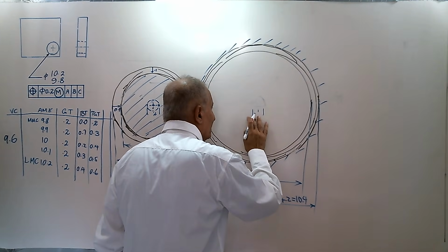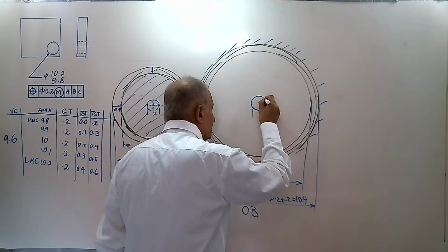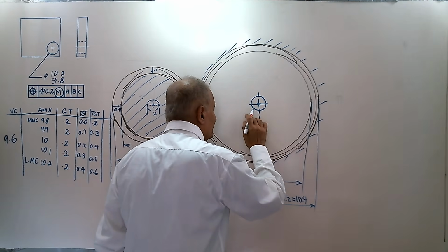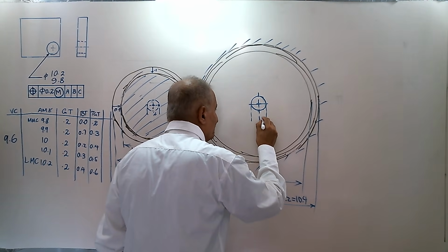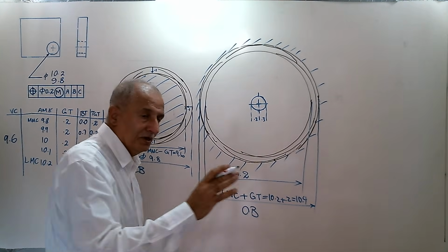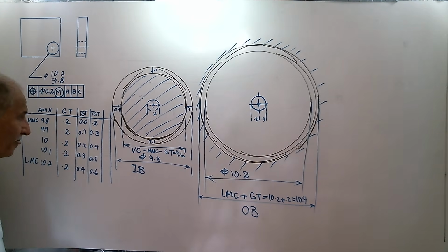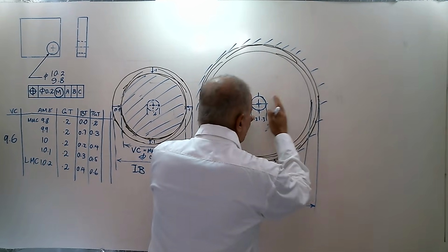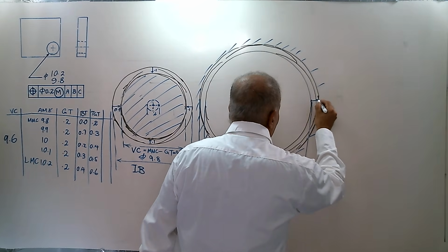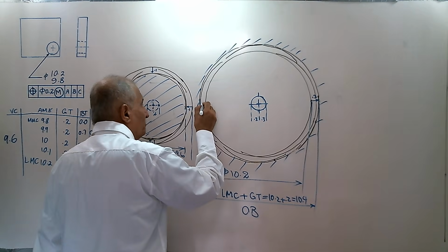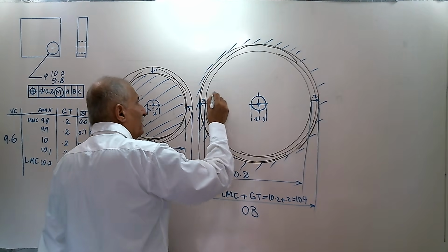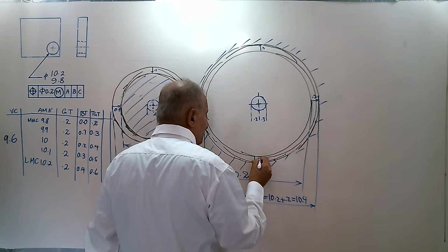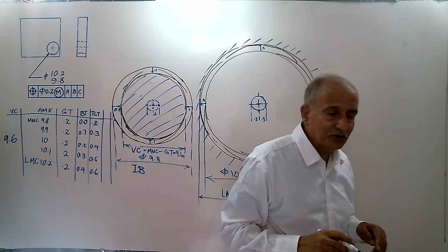we have a geometric zone 0.6, 0.3, 0.3 on all sides. Then the hole with the size 10.2 can be shifted 0.3 to the right side, 0.3 to the left side, 0.3 upward, 0.3 downward, or in any other direction.